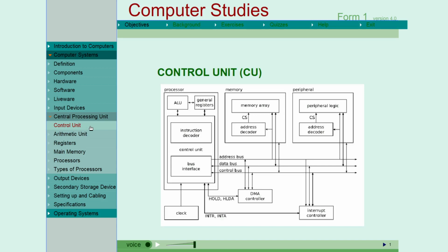When connecting computer peripherals, certain rules should be observed to make sure that the connection is done well. One of the rules that should be observed is the performing of an electrostatic discharge. Electrostatic discharge is the transfer of static electricity from one object to another. Our bodies also produce static electricity, and static electricity that might have built up on the hands can be discharged by touching earthed metallic objects or wearing an anti-static wrist wrap. Also, make sure that you disconnect devices from power to give you room to connect the additional peripherals.